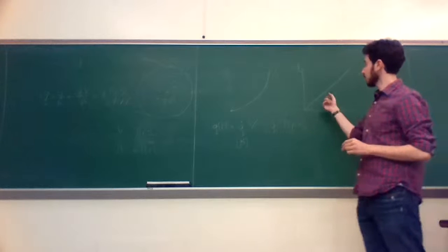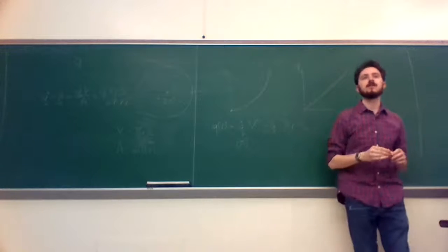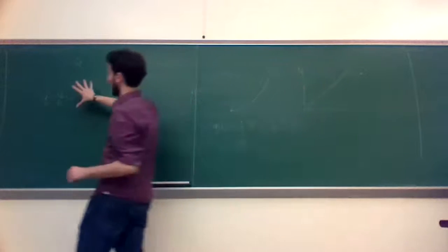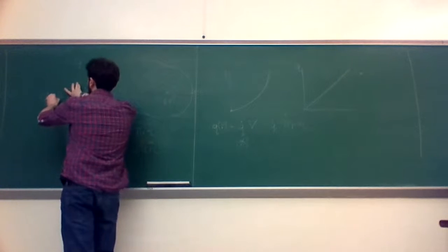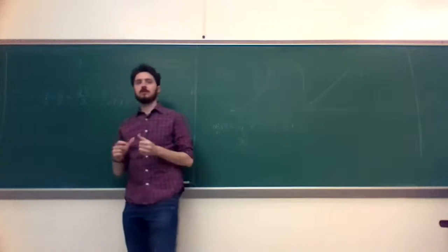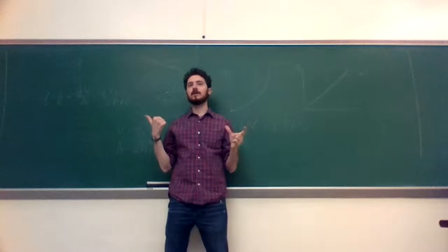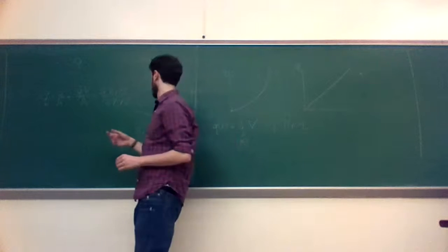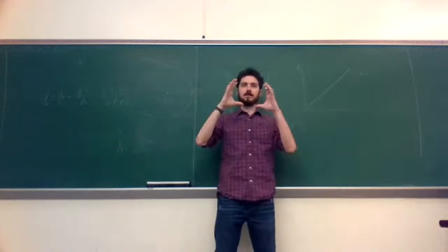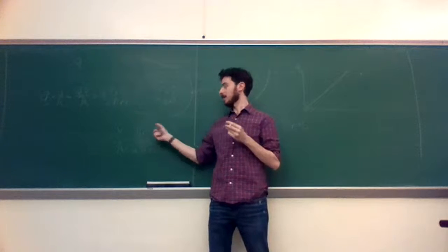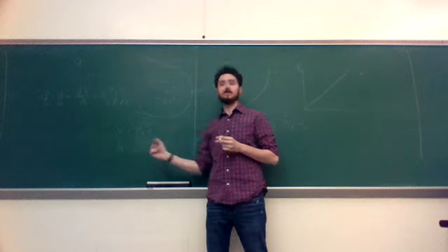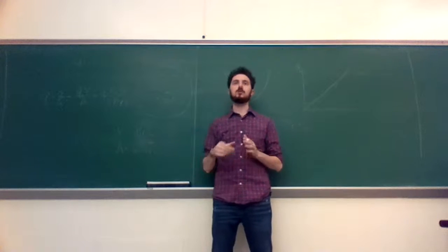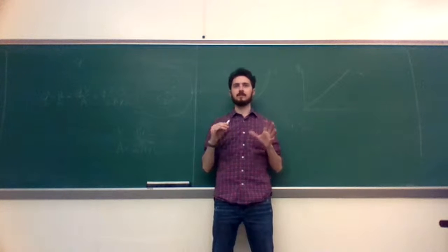Okay. Challenge question. So heat flux. Heat flux is exactly equal to your heat rate, Q, over your area. Now, as your radius goes out, your volume increases, but so does your area. However, they don't increase in the same way. So your volume of that control volume, pi r squared L. Your area of your control surface, right, which is the thing that's bounding the control volume, increases as 2 pi r L. So everybody remembers that?